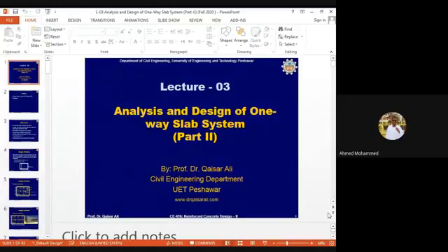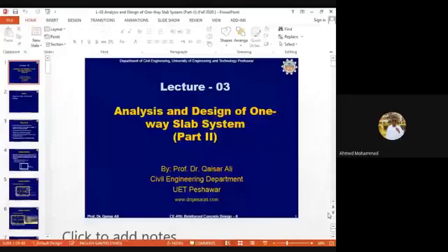The top bars were 2 bars. And when you saw a section near the support, what did you see? The upper bars became 4 and the main bars became 2, because he turned 2 of the main bars up by 45 degrees to support the upper bars. He did it because he said that the shear at the support is maximum, so it needs to be supported.